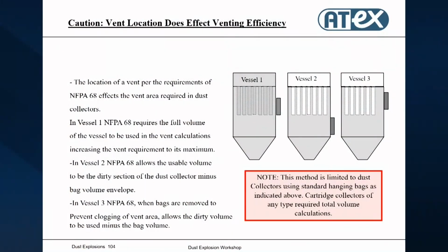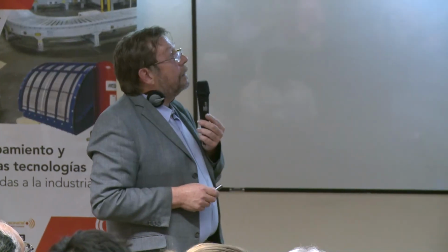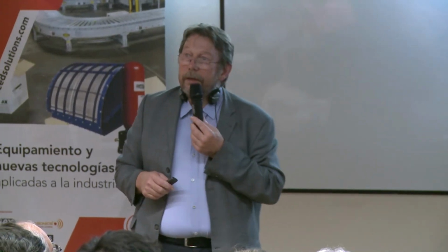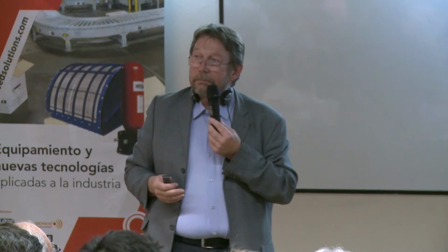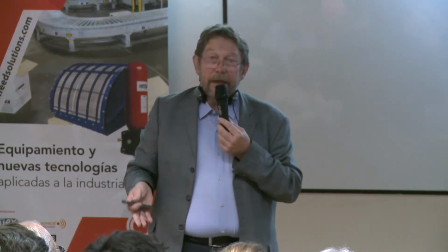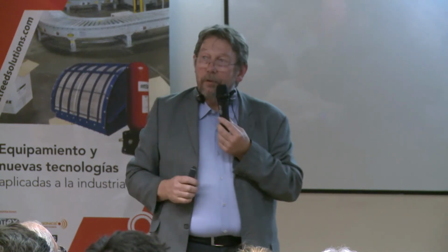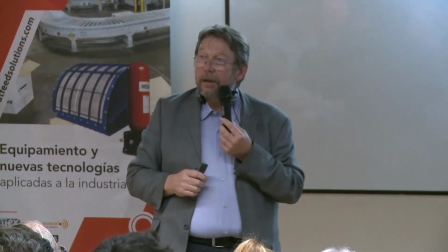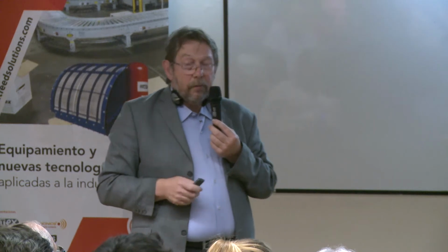Just a very few practical things now, and this we also have done in NFPA, based mostly on these 250 filter experiments that I talked about earlier that we did in Norway, because we found that in a filter you do not need that much vent opening, because you have filter bags that consume energy. You have the clean air side where the explosion pressure can be dissipated, and therefore we found that